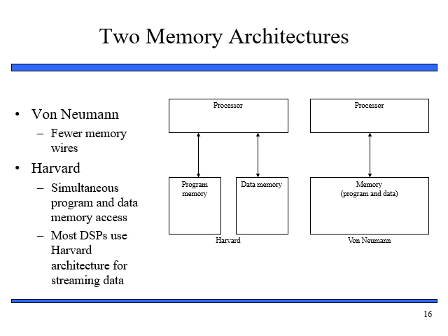On the other hand, the Harvard architecture has separate program memory and data memory. You can access program and data simultaneously in Harvard architecture. Most DSPs use this architecture. Even the 8051, which is a very popular microcontroller, has this Harvard architecture.